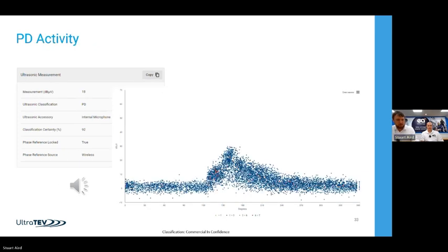Conversely, looking at another measurement from the same type of transformer, you can press play on this one. You'll probably hear that arcing and sparking. So with PD, the physics around the PD discharge site will change with every cycle. So you won't get an exact repetition. It'll be a slightly different amplitude discharge, a slightly different part of the cycle each time it occurs. And that gives you that nice arcing, crackling sort of noise you can hear there. Effectively, it's a spark we're listening to.